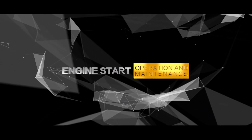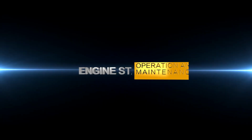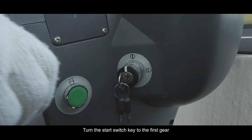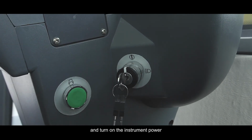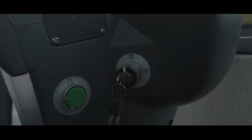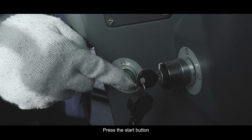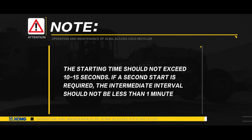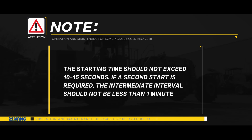Engine start. Confirm the following. Turn the start switch key to the first gear and turn on the instrument power. Press the start button, switch on the starter mode, and start the engine. Note: the starting time should not exceed 10 to 15 seconds. If a second start is required, the interval should not be less than 1 minute.